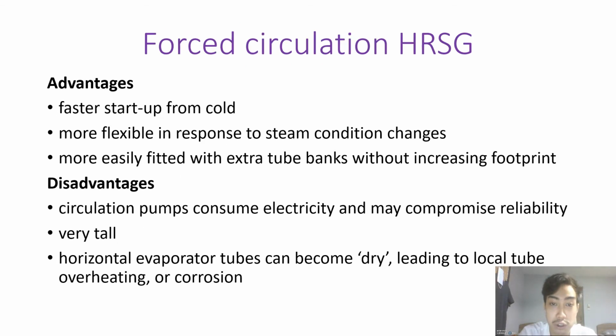Hi, my name is Jared Joshua Pinto, ID 23648, and I'll be presenting on forced and natural circulation of HRSG and HRSG application in the energy industry. Firstly, forced circulation HRSG. In the past, vertical HRSGs were often known as forced circulation HRSGs because of the use of circulating pumps to provide positive circulation of boiler water through the evaporator sections.